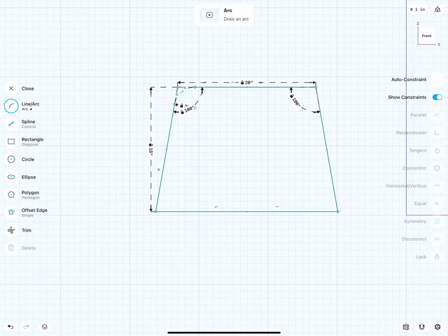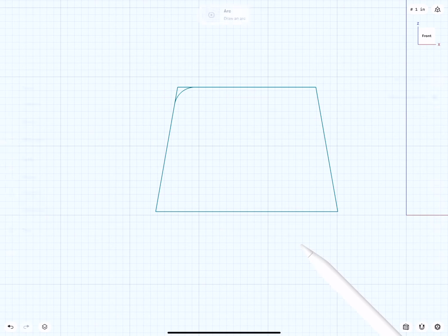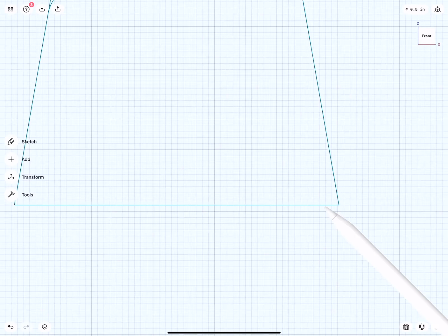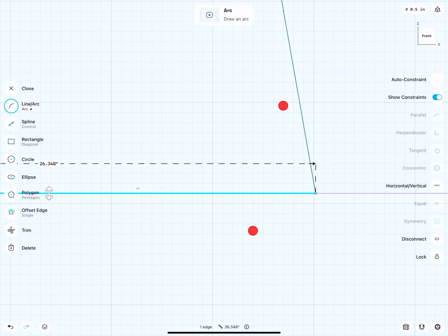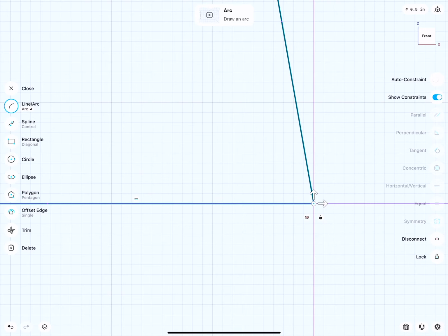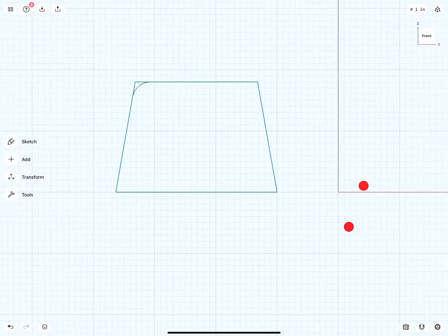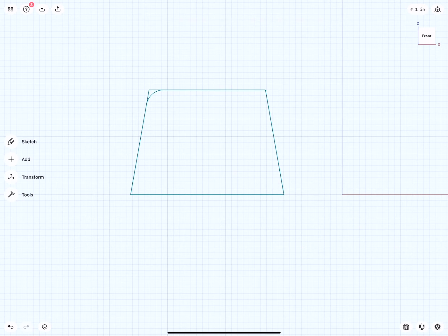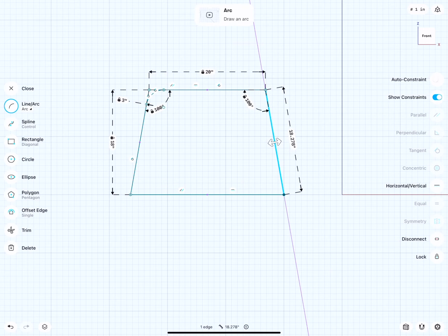When I zoom out a little bit, you notice that actually the sketch moved up a little bit. So if you want to prevent this, we can do the following. I will select this point, move this to here, and then this point I will simply glue in place. So everything of the sketch can move, but this dot will not.